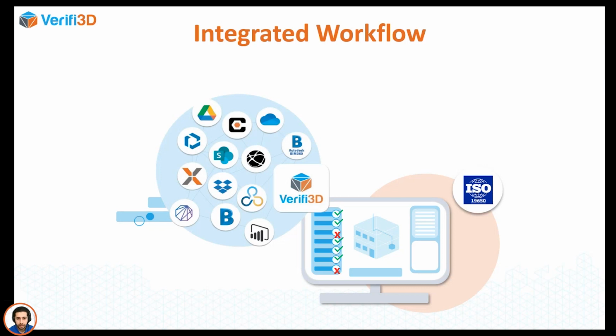All of this is in compliance with ISO 19650, because nowadays this requirement is the one that streamlines our information management through BIM software. And not only CDEs, but for issue trackers, Verified is also connected to different issue trackers from BIMcollab, Forma Connect, or BIM 360 issues.